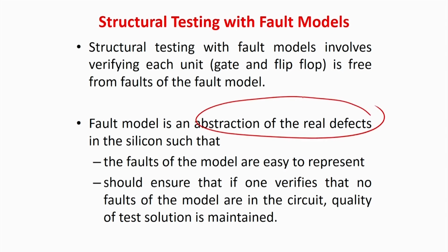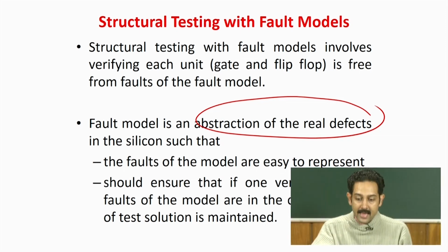If you go for transistor level testing, or physical means like layout, testing of the devices at the fabrication level, like testing of the vias, testing of the interconnects, that may blow up all the algorithms and the time required to do the testing. It is also not required, because it has been found that if you have really good quality fault models, then the second point should hold: if one verifies that there are no faults of the model in the circuit, then the quality of test solutions is maintained.